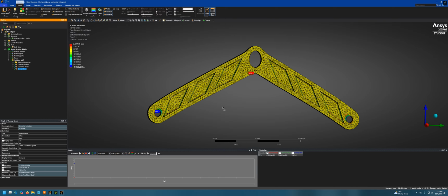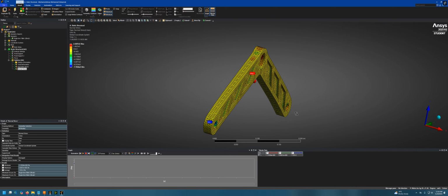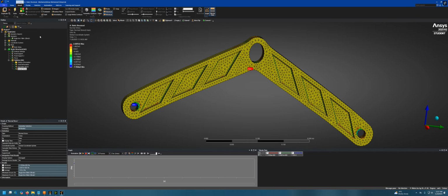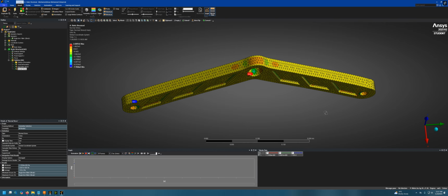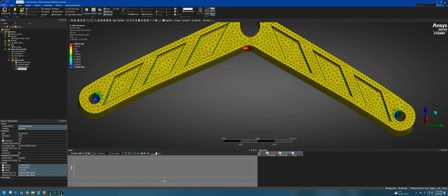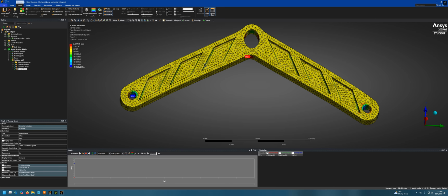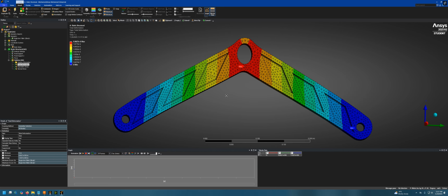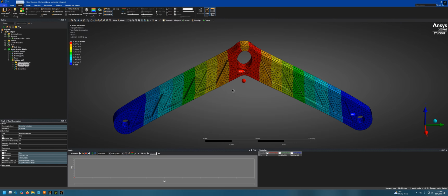But that is how you get a step file that you export from Fusion 360 or something else, and you do the analysis. I was running into issues where it wasn't defining the material properly, and also there was just a limit on the number of mesh components, triangles you could have. So maybe that'll help someone else. I'm sure when I forget this in a month, it'll help me.